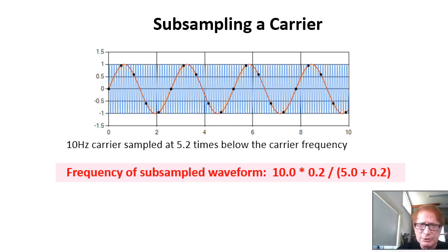With a traditional heterodyne radio, there's a lot of hardware involved in the down conversion of the information encoded under the carrier. Also, noise and other corruption is contributed by the nonlinear heterodyne process, where two waves are multiplied together.